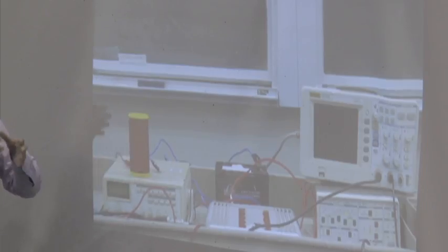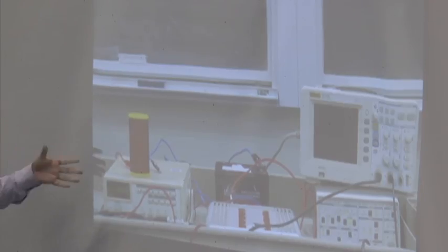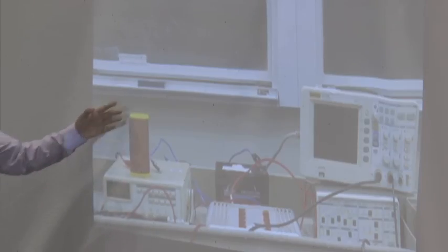And an EMF is expected to develop around that secondary coil. A mutual EMF, a mutually induced EMF. That EMF is really small because this is air inside and the fields are really small. So I'm going to amplify that voltage by another amplifier, and I'm going to filter it a little bit. I'm going to signal condition it so that the waveform looks nice, and then I'm going to display this on an oscilloscope. Okay, I hope you understand the scheme of things here. You get it? Alright. So I'm going to turn on things for you.